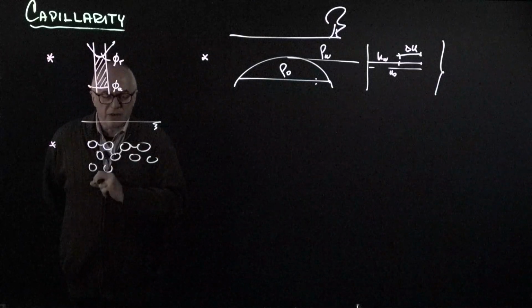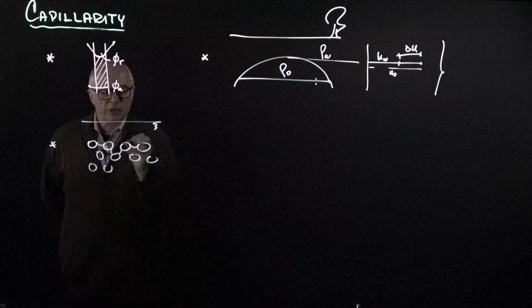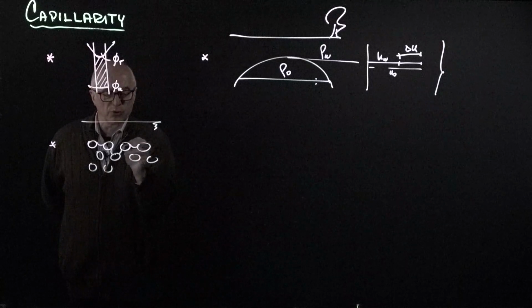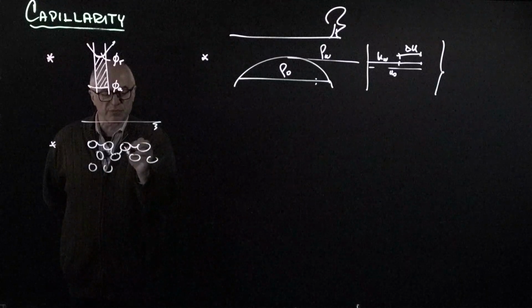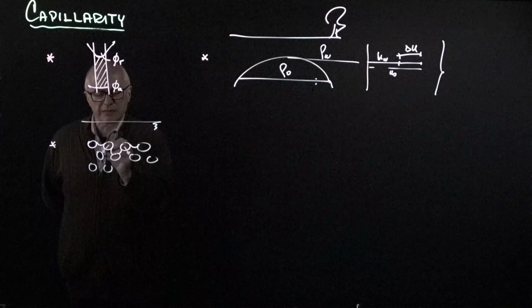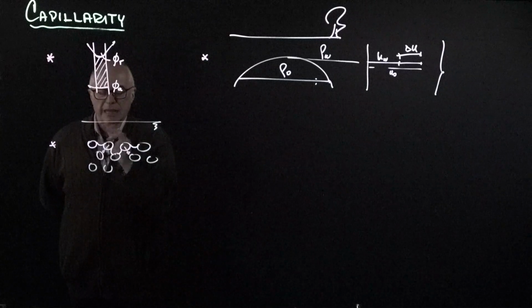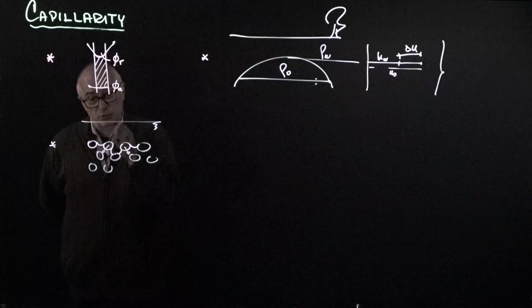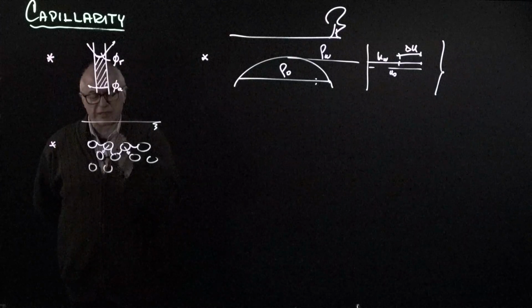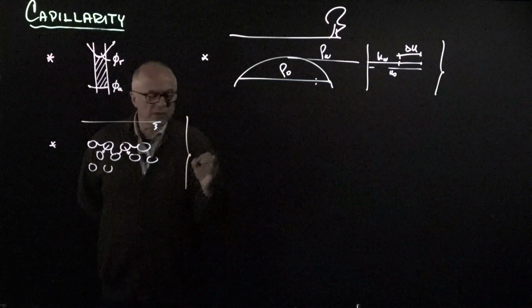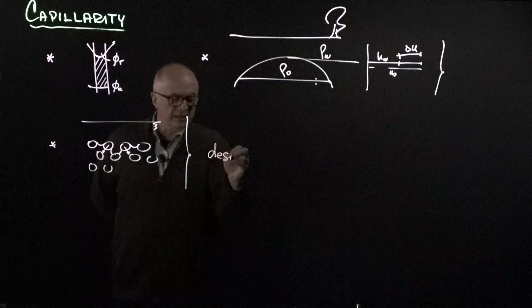And now if I look at that instant, actually this particle is being pulled. Look at the summation of those two forces. It's being pulled in this direction, this one in this direction, and actually that pore is increasing in size. And I can continue now. That leads to preferential invasion. And if I continue this, I'm going to understand the concept of desiccation cracks.